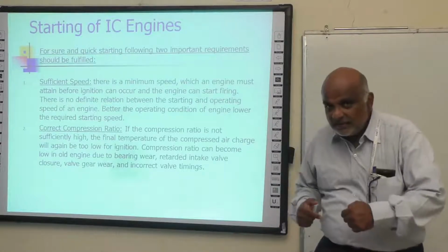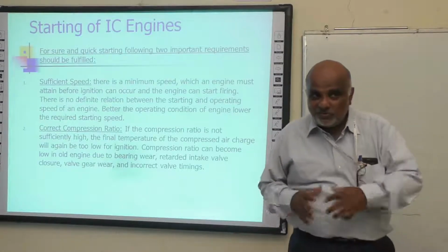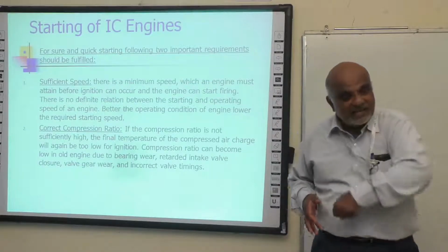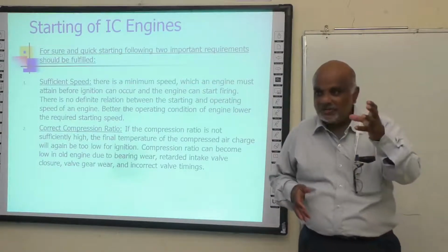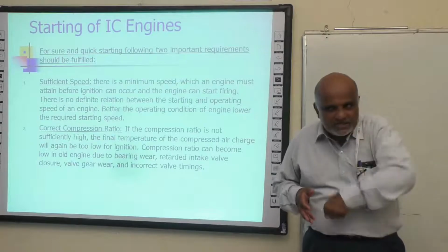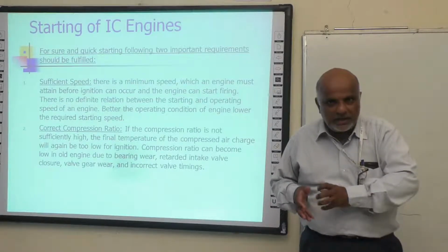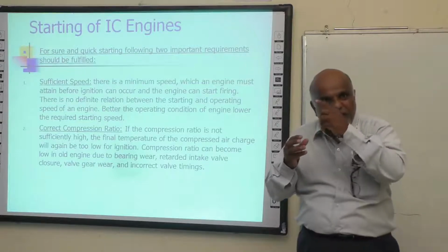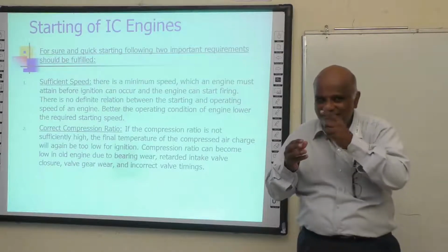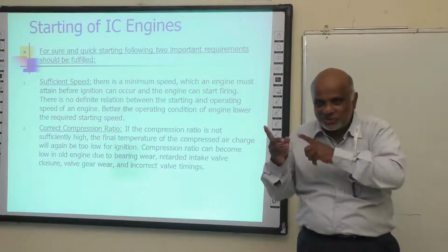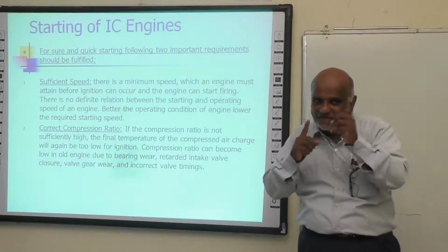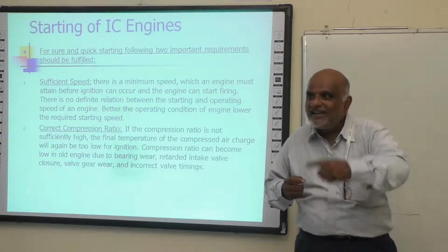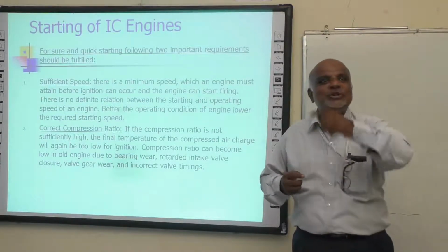Now here, can you tell me what was happening inside? When you did the pedal kicking, when you pressed that pedal, which had a sprocket arrangement, a gear was engaging on a wheel. It's called a flywheel. Now in a 2-stroke engine, that is where the flywheel is, and in a 4-stroke engine, that is where the flywheel is. It engaged the flywheel and made that engine rotate.